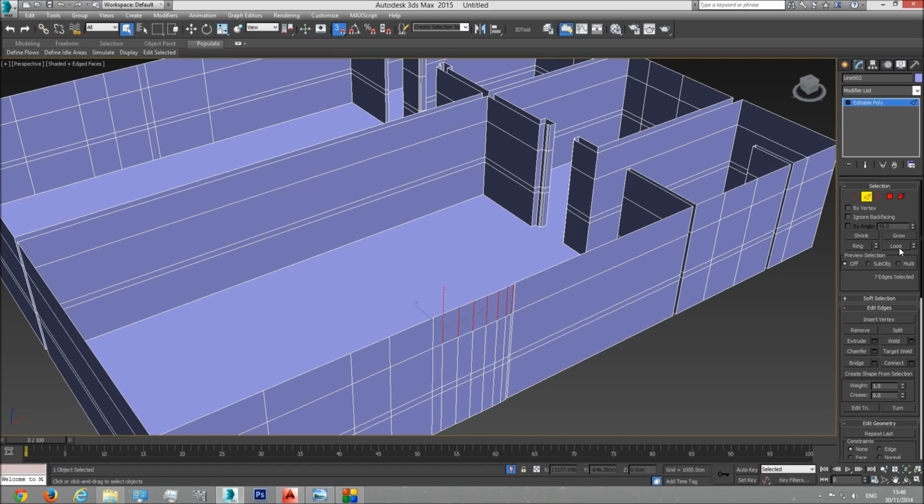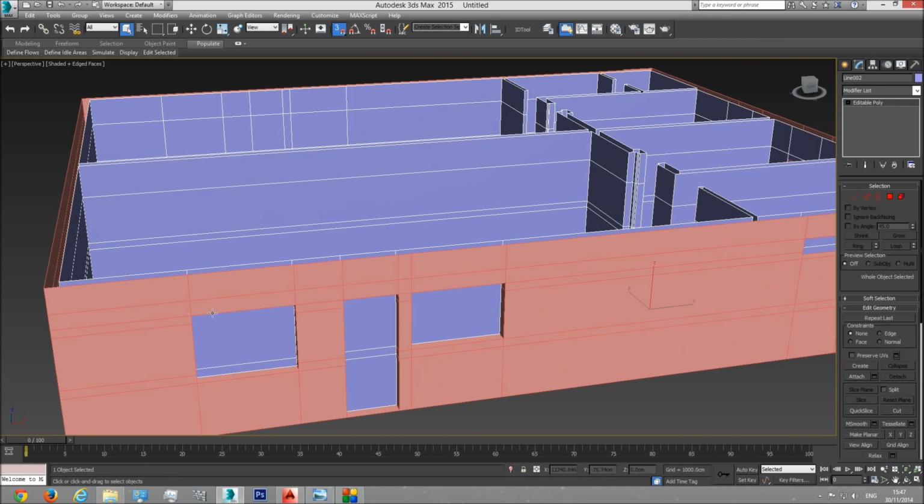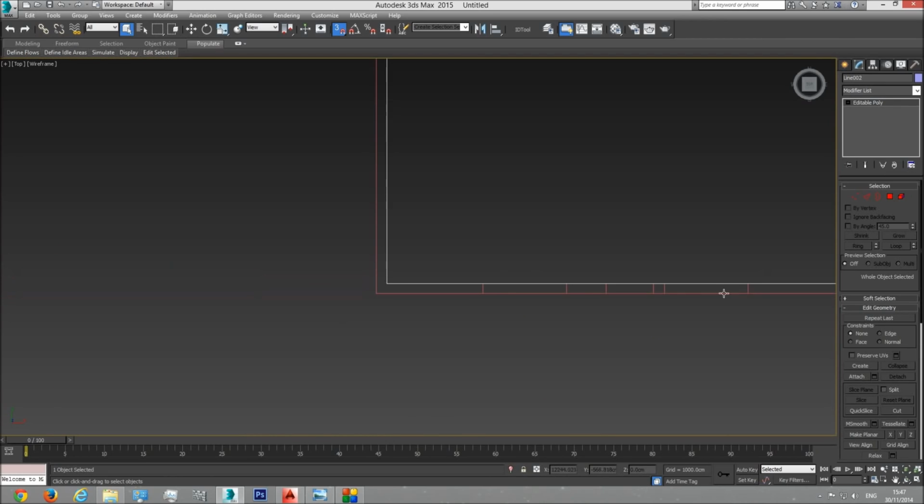I'm going to click loop, so this will select all the lines in these lines. I'm going to Control click on vertices. This will select all the vertices that touch the lines we selected. Now I'm going to go back to Edge, hit Backspace to delete the lines, go back to Vertice because the vertices are not deleted yet, but they are selected. I'm going to Backspace delete them. And now I'm going to unisolate everything. So now it's fixed, everything is straight.